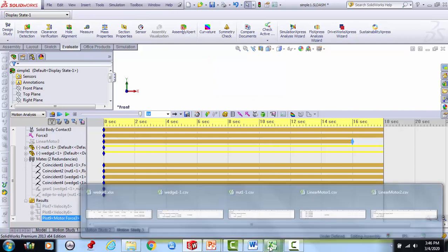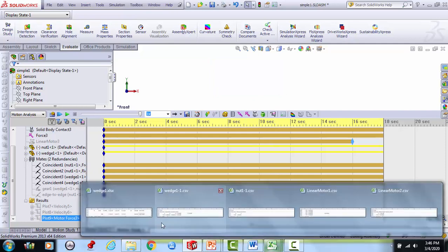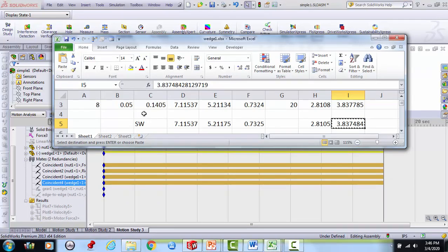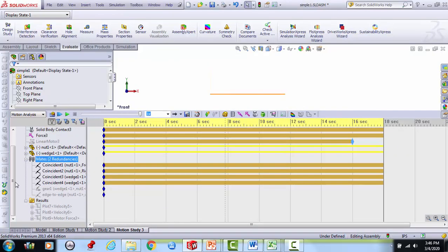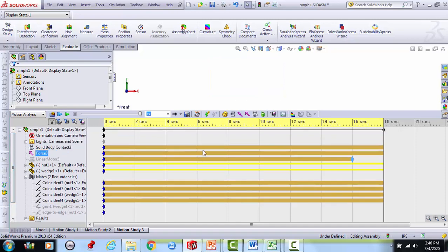It has to do with, when you look at lowering the nut, what the friction factor is for it. If it is less than the tangent of lambda, it's going to be back drivable. If I make it more than the tangent of lambda, this is for lowering, let's say 0.2, it might stick. That should be self-locking when I let go.